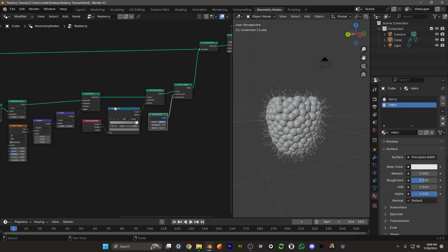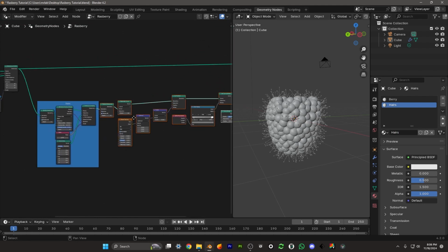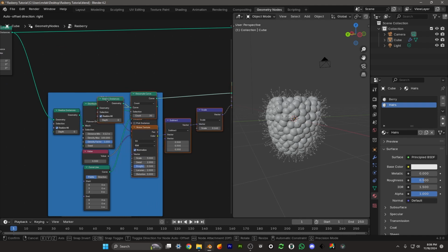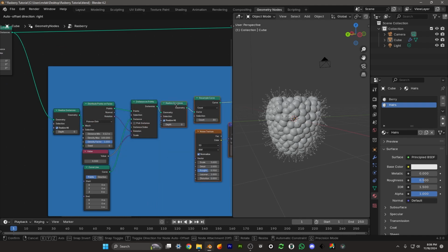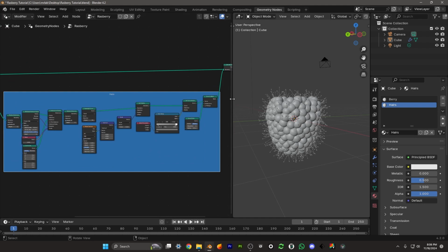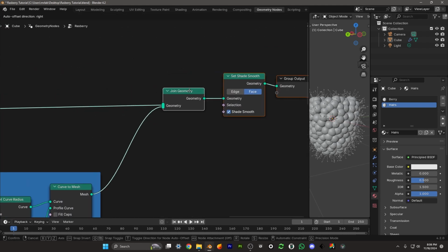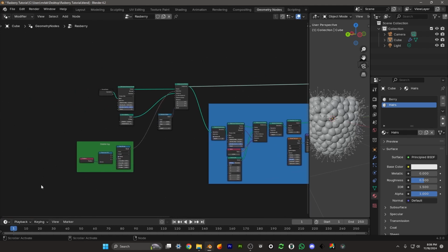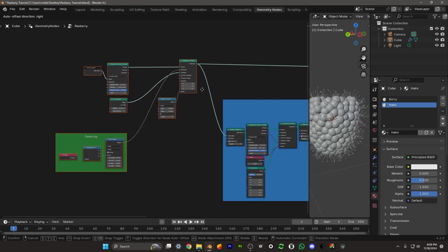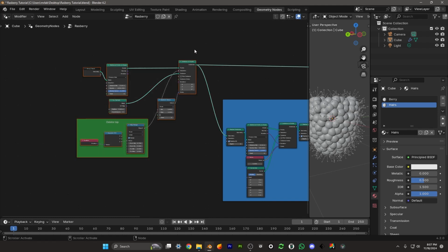And what we're going to do over here, all of these nodes at the bottom here that we've created, I'm just going to take them and drag them into this blue box here. And that's just part of the hair. So everything in here has to do with our hair. And this join node here just joins everything up. And then everything here is related to making our berry. So in fact, we can grab all of these guys over here and go Control J and put them in their own box.